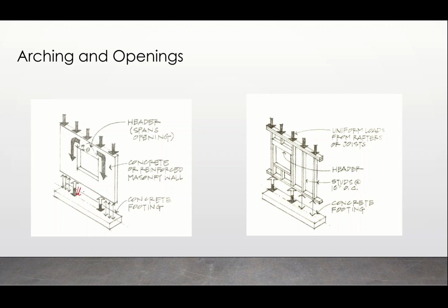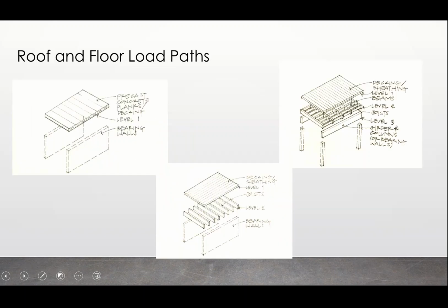As you can see, underneath the window and the opening, it can't hold anything in compression. There would be glass there, and so it's not going to be holding anything to the concrete footing. Same thing for any kind of window base, that design: uniform loading on top, angling to get around to get back to the concrete footing without damaging that opening or utilizing it as a structural piece.